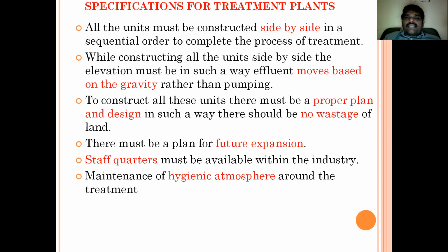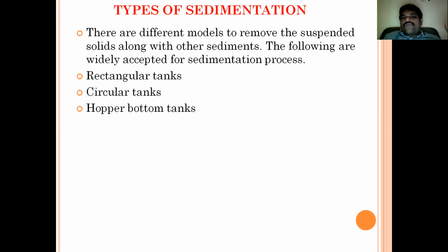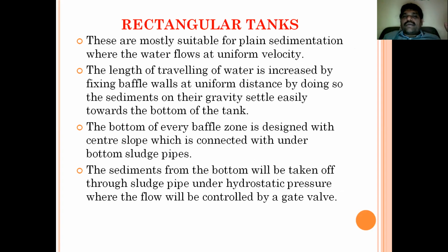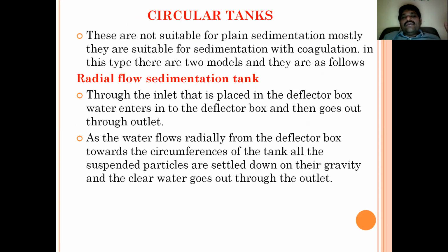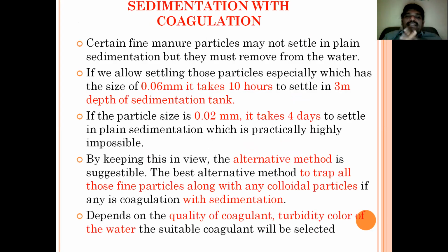The particles that we were unable to remove from the bottom fail to settle because of low weight. Weight here means size. If the size is 0.06 mm, it takes 10 hours to settle in a 3-meter depth sedimentation tank.